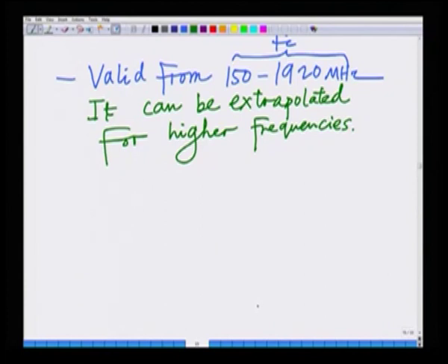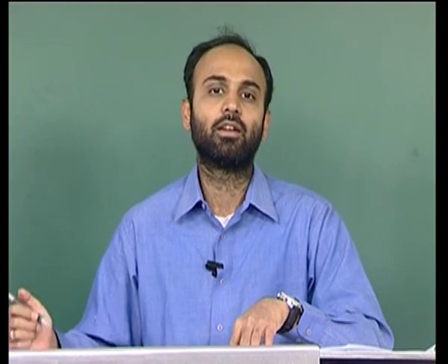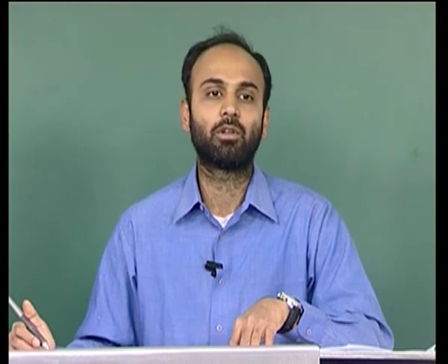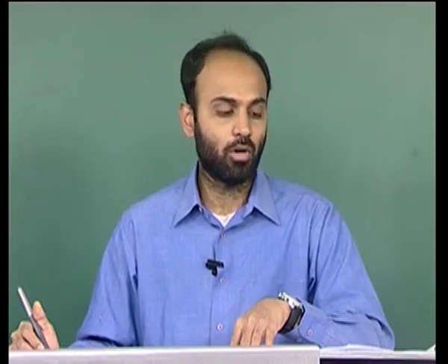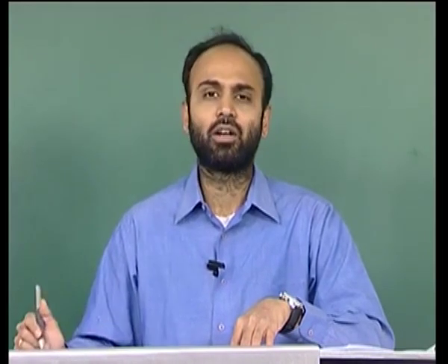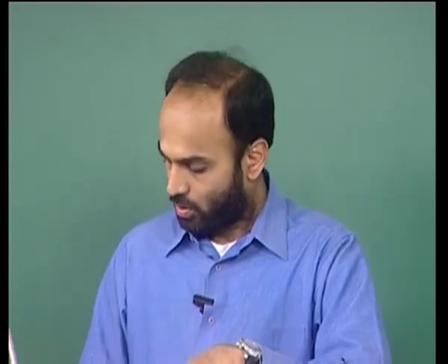So, what you are saying essentially is this Okumura model is one of the more popular models employed to characterize signal strength in urban practical scenarios such as urban, suburban, cellular scenarios, and it is one of the most widely used analytical models. It can be used right around the 200 megahertz range, and we are going to use it for the 2.5 gigahertz range also, essentially covering most of the cellular band. Okay. So, what is the Okumura model?